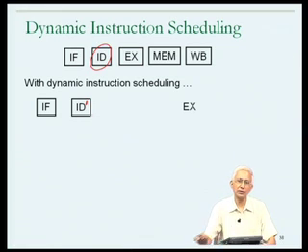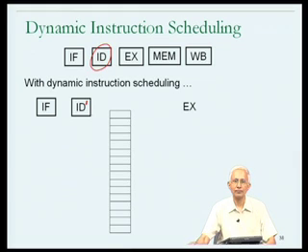Subsequently, all of those instructions one by one would execute, but during the time that they are being considered for being scheduled as the next instruction to execute, they would have to be remembered, and hence there would be some kind of a hardware data structure, some kind of a memory storage with associated logic within the processor, where instructions could be saved after they had been decoded for consideration for scheduling.